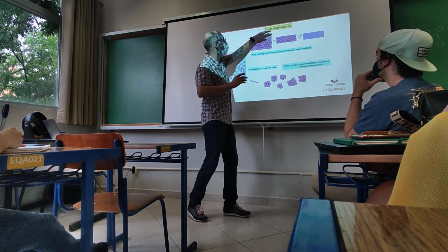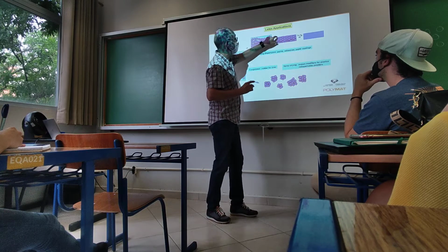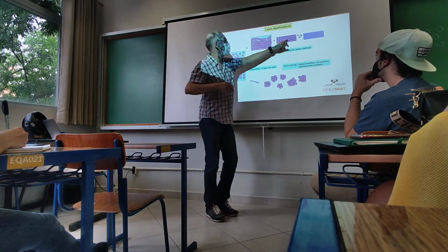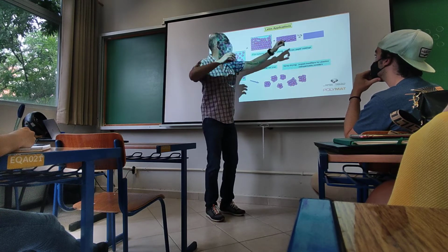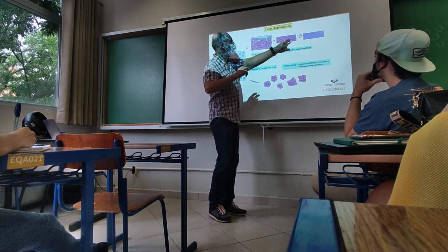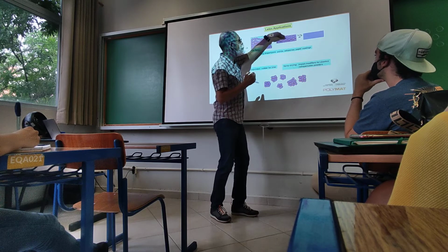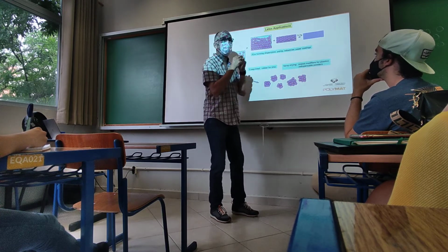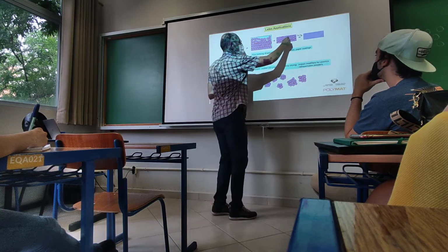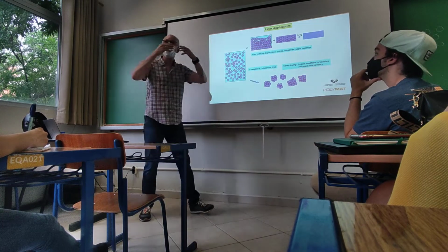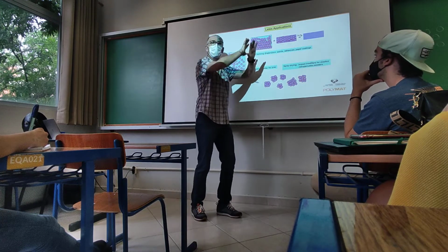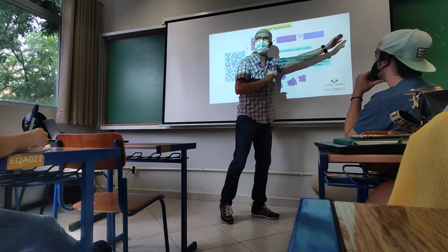I will show you now a nice video that shows this. The particles, as the water evaporates, will pack in this hexagonal structure. And now, if the temperature at which we are producing this film is higher than the TG of the polymer, the polymer close to the boundaries can interpenetrate, can diffuse, and the boundaries will be lost, and you will get a coherent film.